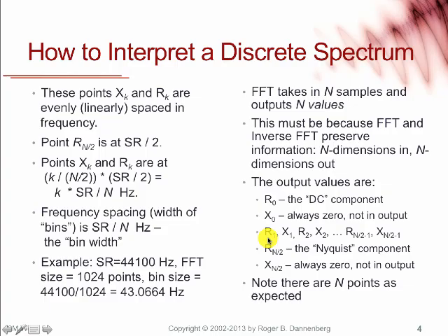So location 1 in the array is r sub 1, and location 2 is x sub 1, and then we just alternate real and imaginary and fill out the array until we get to the last pair of coefficients, the r and x with subscript n over 2. This is the Nyquist frequency, and it turns out there's only one Nyquist component, which is the real, or cosine, component. The reason for that is sine starts at 0.